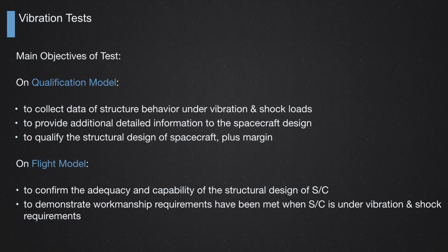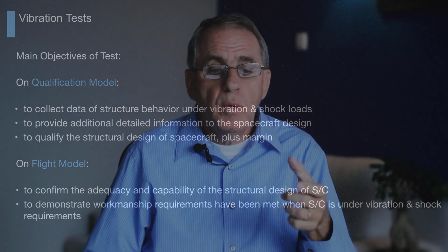Okay, let's talk about vibration tests now. Vibration tests, as I said, are very critical because they have to prove that the spacecraft will survive the launch phase. Typically we perform vibration tests on two main models. On the qualification model, we collect data on the behavior of the structure during vibration and shock loads. Doing that, we can qualify the design of the spacecraft. And because we use a margin, we do a better qualification. We vibrate more than expected during the launching phase.